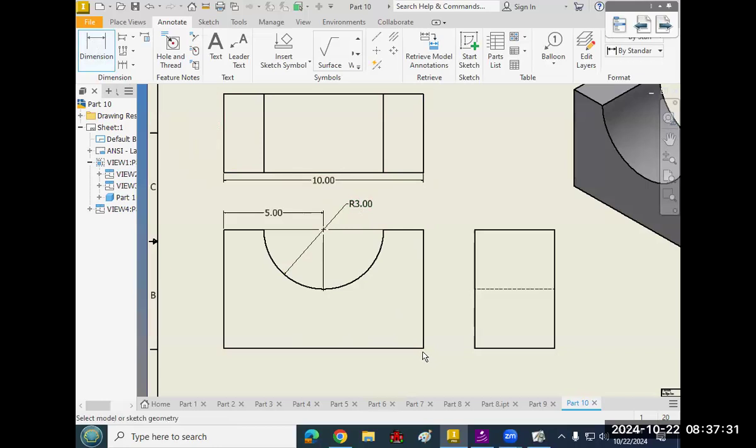Okay, then height, the first thing that happens is the bottom of this, which is what this hidden line is dimensioning or showing. And we don't need either of these because this bottom edge of the curved surface is just whatever's left over when we make that cut that we know the size of.